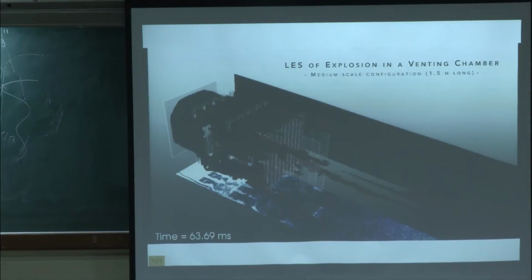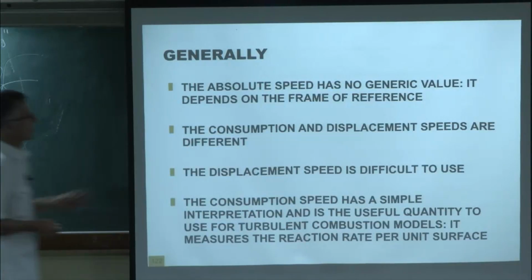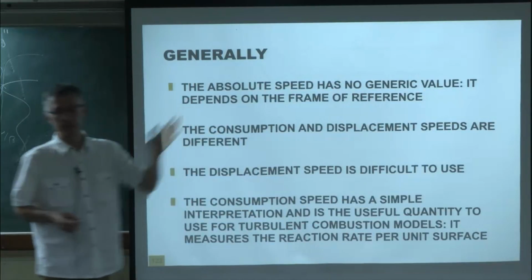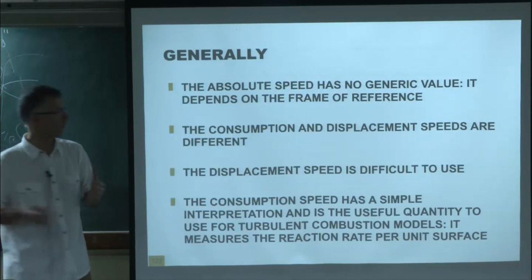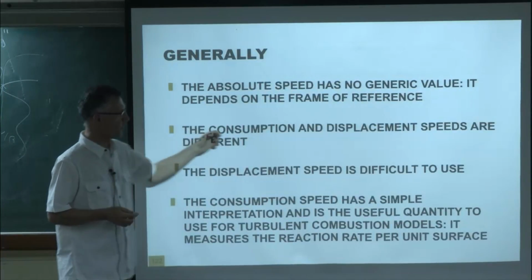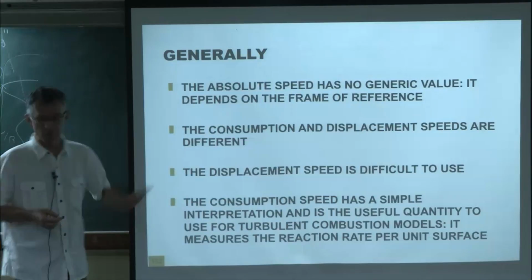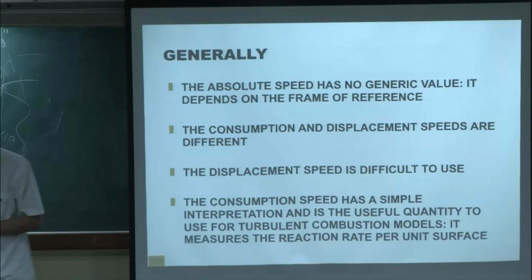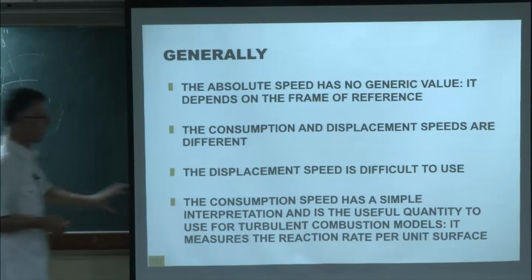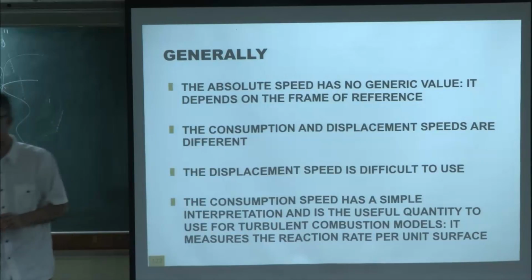So to conclude on these flame speeds, in general, the absolute speed itself, you don't use it because it depends on the reference frame. The consumption speed is the one you want to use. The displacement speed, I would say it's a difficult quantity. I would suggest that we work with the consumption speed as much as we can.